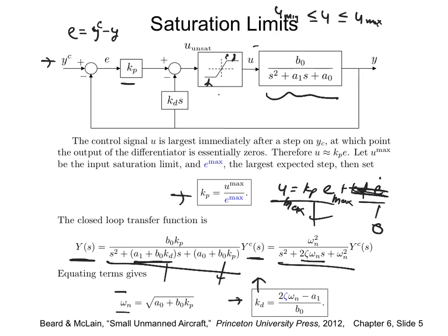Okay? Questions? No, right? So, zeta is the quantity of interest here, because omega n comes from here and zeta is defined, 0.07 or 0.7 or 0.8, whatever gets you the desired behavior you need. So that's the damping ratio you have. Okay, so this is the standard approach that we will apply throughout the design of this.